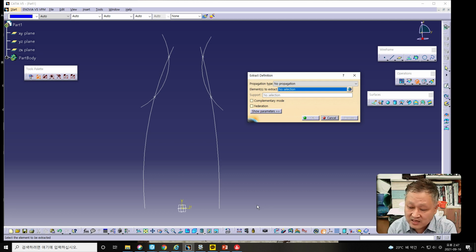If it is not extracted, the curves move simultaneously. Therefore, they could not be made separately from each other. Therefore, we should separate them with the extract button. Therefore, please select this one first, and if a curve is selected, then its color should be green.